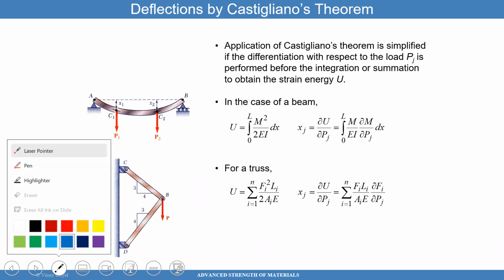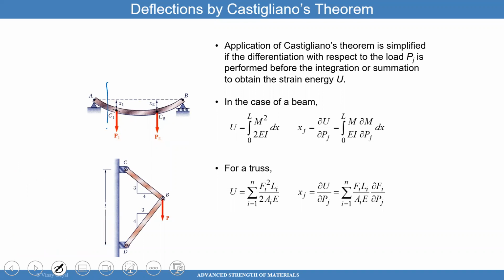Can I do a cut there? Do you guys know how to do that? Do the cuts and then calculate the moments in that section? So you agree that the moment calculation is going to be a function of loads P1 and P2? Are you guys following me or you're lost? Yeah, it should be obvious, right?